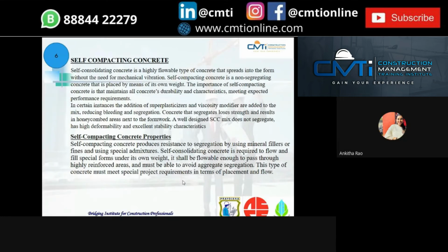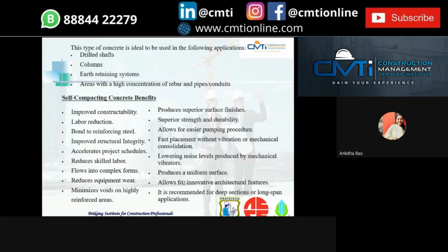It flows under its own weight, not creating any air voids, and it can be easily used in drilled columns, earth retaining systems, and areas with high concentration of rebar and pipes. Where we have pipes and all, we can't do the mechanical vibration that easily. So using self-compacting concrete, we can achieve that too.